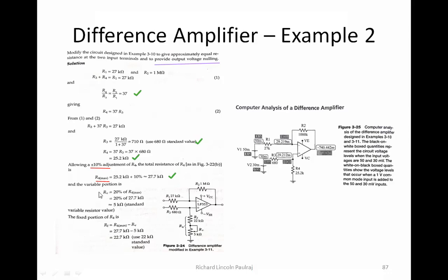So that's why, approximately, we're going to use 5 kilo ohms. Okay, because that's the standard, and I'll be omitting this 0.54 kilo ohms. So approximately 5 kilo ohms is going to be my value of RV. Okay, this RV, variable resistance.